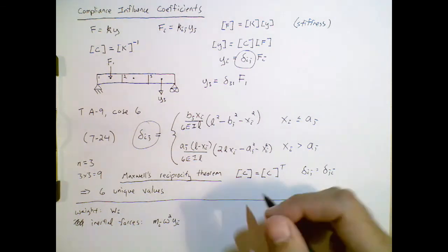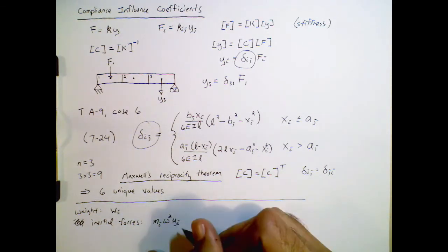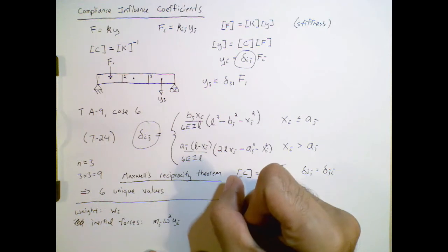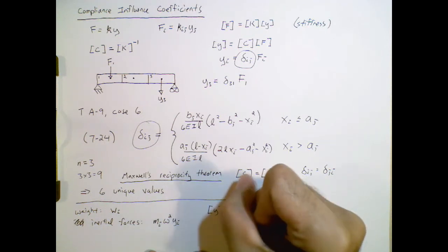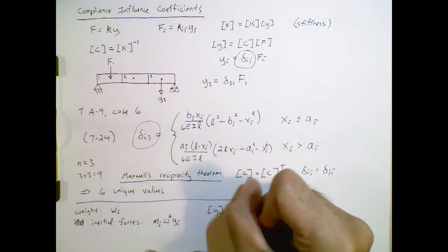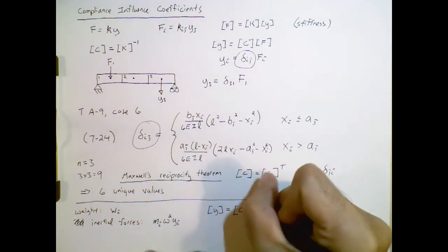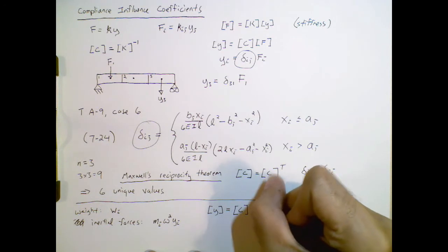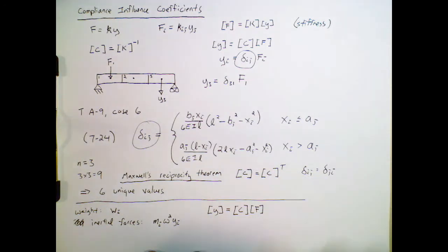Now we can take these and write a system of equations where the deflections at each of those segments are going to be equal to the compliance matrix times a force vector.